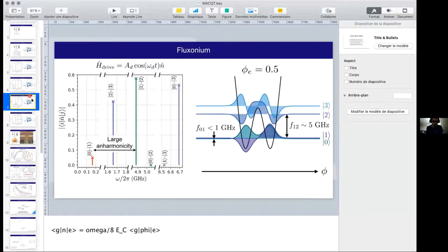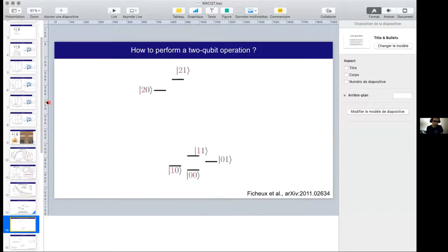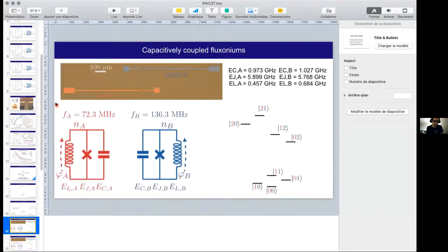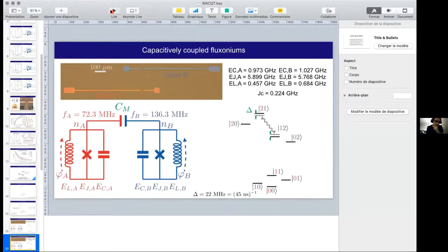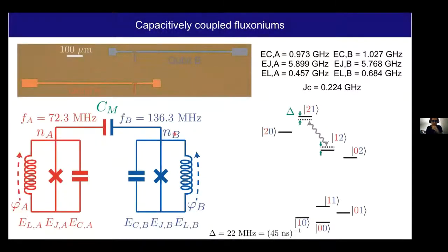Yeah, right. So this is just a regular capacitive coupling between 2 qubits. That's similar to what can be achieved between capacitively coupled transmons. So it's entirely determined by the relative position of the two antennas, and the capacitance value that we have is comparable to the one that people typically use with transmons. So yeah, it seems like you don't want to make it very big. Is there a reason why?